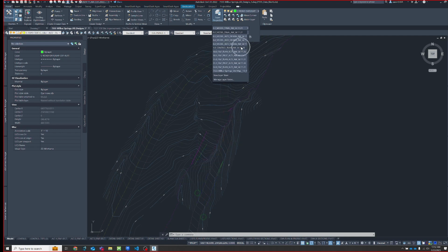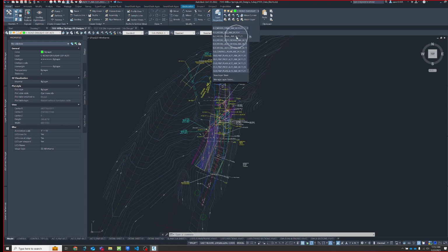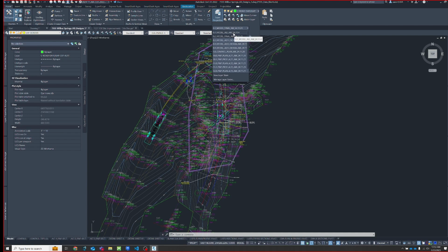This one was more for the control sheet, no proposed items. But this goes through my 3 design alternatives. It can be a really handy thing for, say, presentations, quickly showing a client something, quickly talking with a PM or discussing. They do take a little upfront time to control the layers and save. That's one setback of them, but once they're set up, editing in them after the fact gets easier and easier. So that's just me using 3 different design alternatives, and then I go back to my final model space when I'm ready to plot.